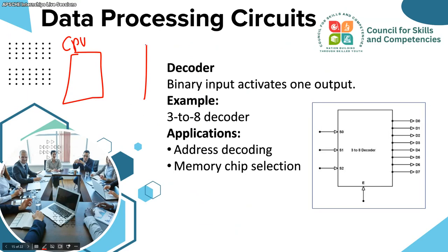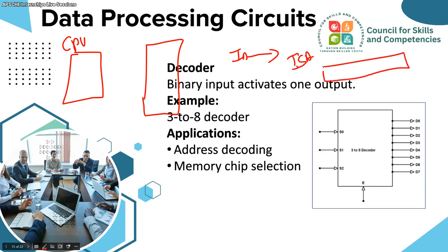So now we come to that part. The CPU we have, and then the memory we have. I told you that an instruction is compliant to the ISA, so they have 32-bit size or 16-bit size instructions. The CPU wants to understand whether it is an add instruction or a sub instruction. How is it able to understand that?